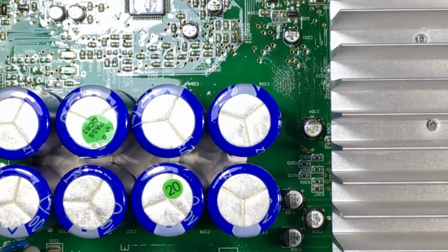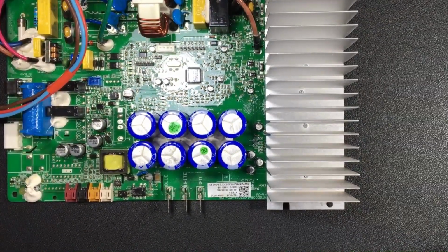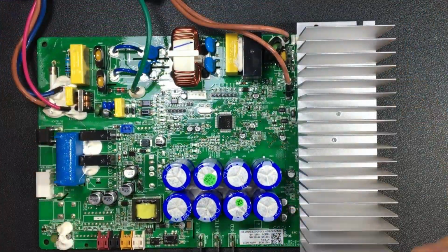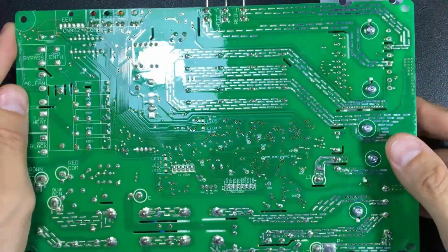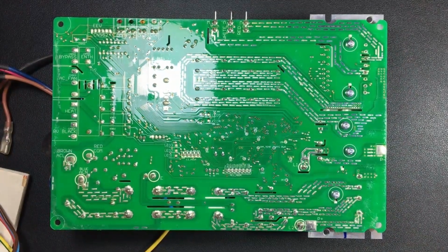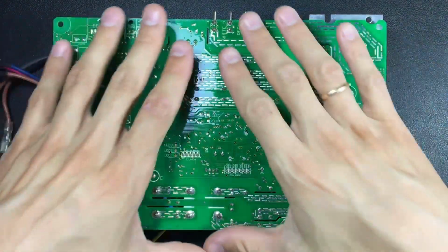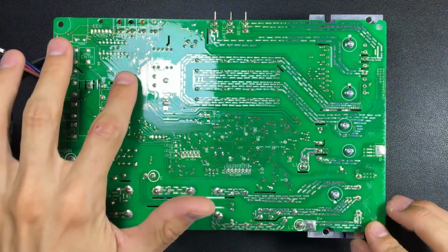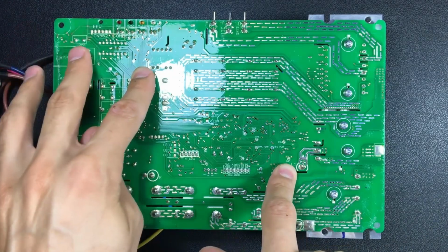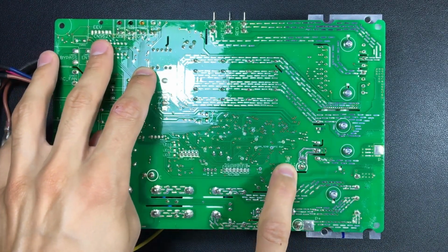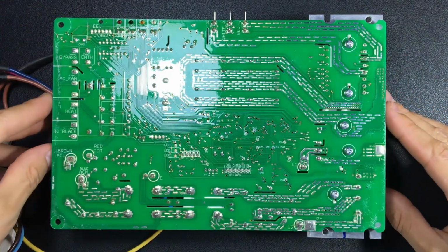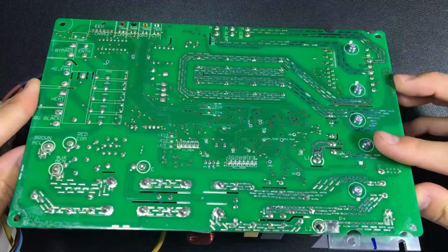Well, the problem with these capacitors is that they are in different parts of the board. For example, in the case of this board, we can make a measurement of those 15 volts located at this checkpoint without disassembling the entire equipment completely. Just by opening the outdoor unit, we already have this area exposed. We can do a test between 15 volts and GND at some checkpoints, and we will see that we have the 15 volts. But to know that those 15 volts do not fall at the IGBT power point is complicated because our test point is on the other side.